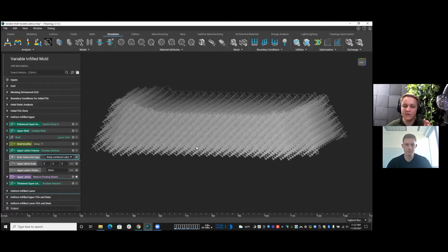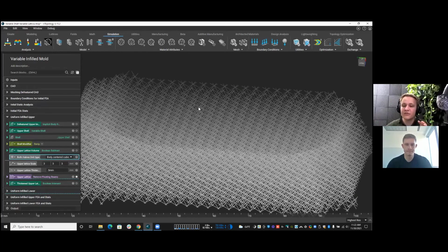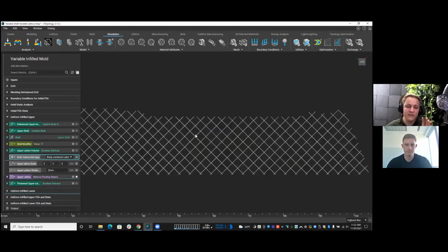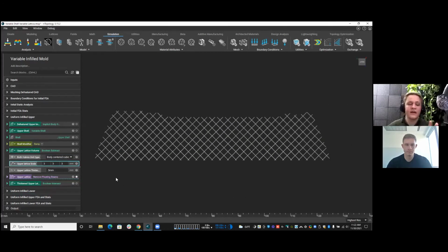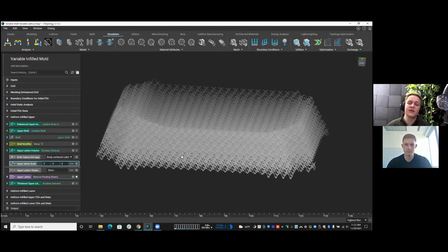And this was in conjunction with Fortify. We like this because of its completely self-supporting nature, right? There's nothing below a 45-degree overhang, so it's completely self-supporting. I chose the unit cell size of 3 millimeters square, and the reason for that is because of the unsupported overhangs, right? So that's the largest unit cell we could do to really make sure this part is completely printable without any added supports. We didn't want to mess with that at all, so we chose that 3 millimeters.